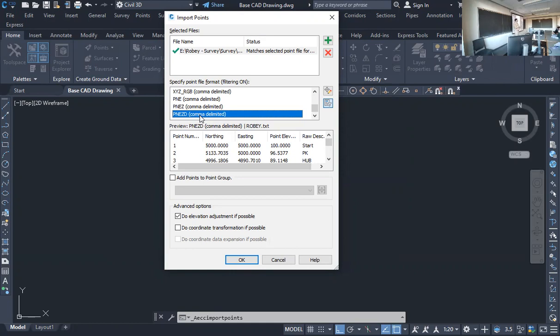I could track it for what I'm using for my surface model. So this is just a housekeeping way of sorting different groups. Or in this case, I could sort it by different crews. Like if I was going to make one parent drawing and we were a big surveying firm, crew 1 through 8 gives me their files and I'm bringing them in as separate groups. Okay.